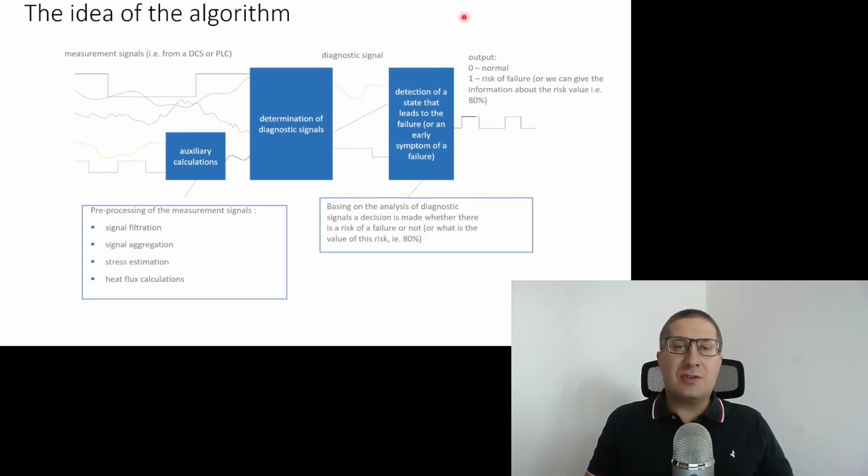What is the general idea behind algorithms that predict failures? First of all, we have a control system, a distributed control system or set of PLC controllers, and we can get the data from these control systems.